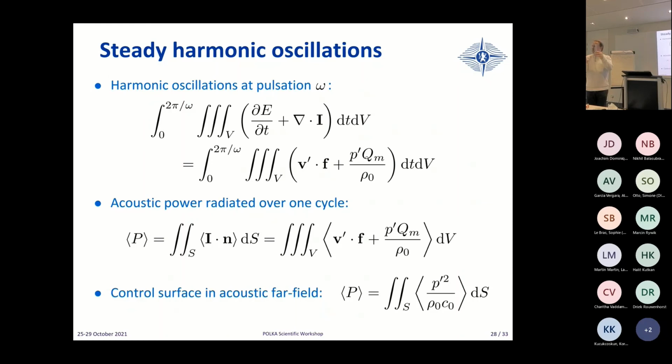And how is it modulated? It's modulated by the acoustic field. Because if your pressure field is pulsating inside of the pipe, you have a certain velocity field that is also pulsating in the pipe. And this small acoustic perturbation is superimposed to the mean natural convection velocity to modulate the amount of heat that is extracted from the grid to the fluid.